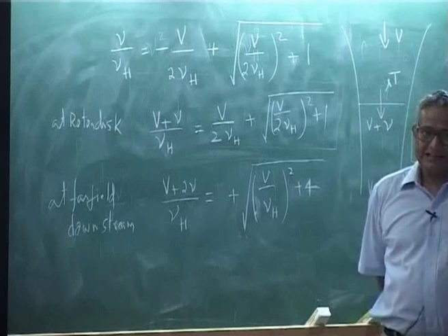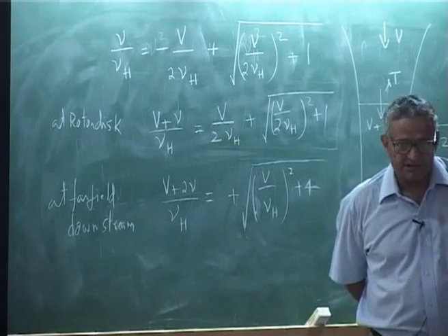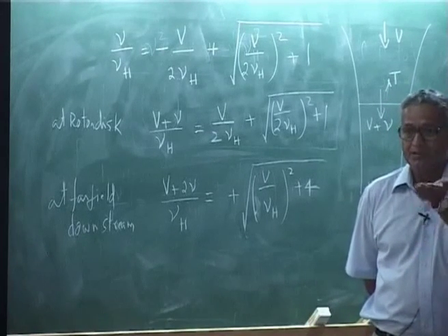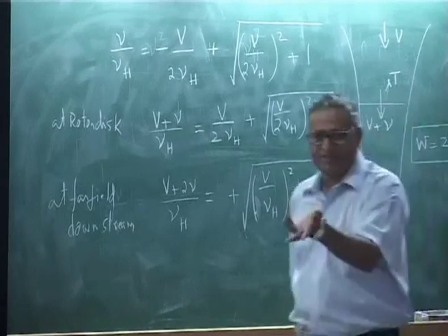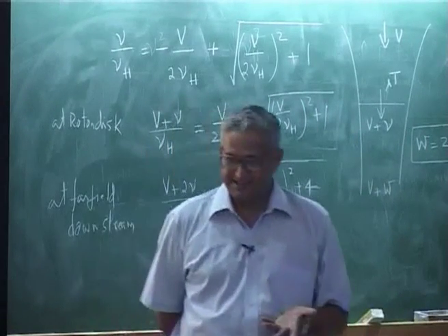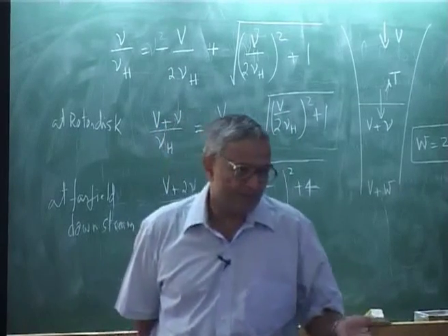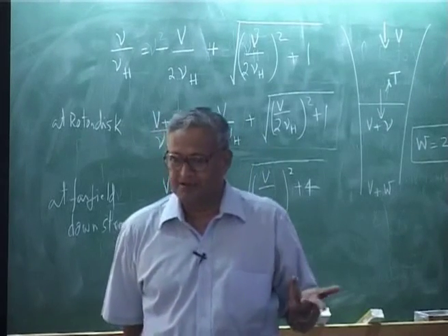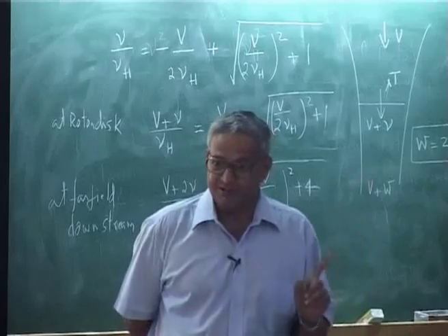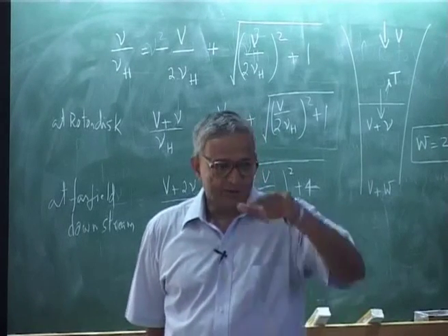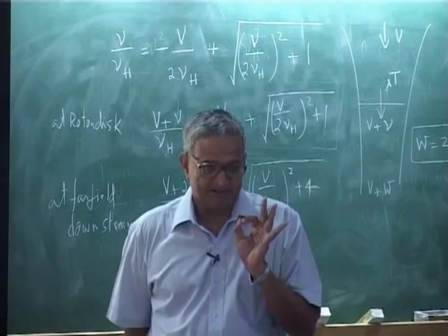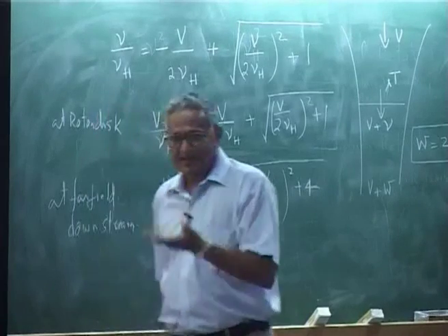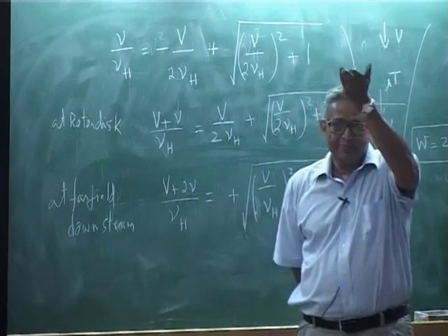So, you will find that the inflow through the rotor disc reduces when you are climbing, because basically you know that the mass flow rate you have increased. You increase the mass flow rate, I have to support the same weight. Since I have increased my mass flow rate, my velocity can be less, that is all, the induced flow, and this same concept will come in forward flight also. So, you will find that value of nu keeps decreasing as you increase your climb velocity.